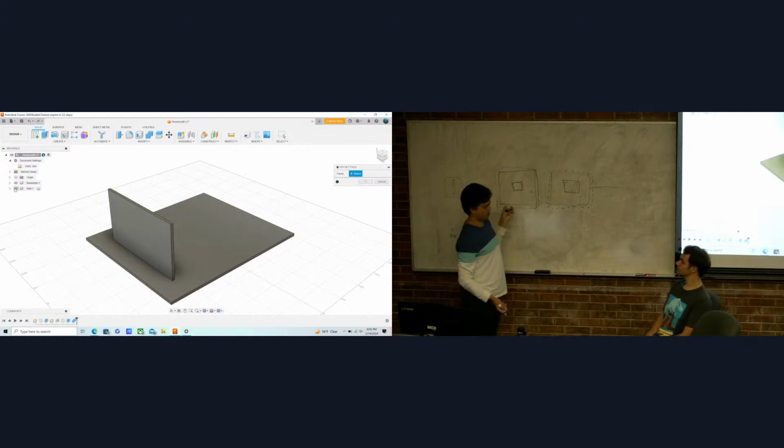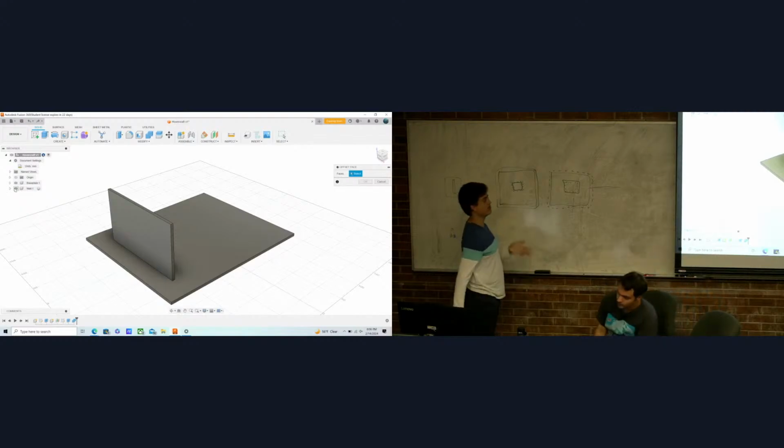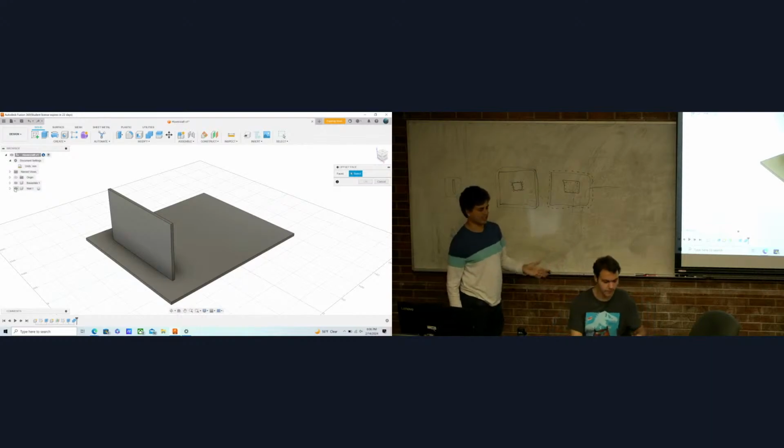And because we use precision wood that is 5 millimeters to a very high degree, if you make your hole 5 millimeters and then you cut it, the hole is actually ever so slightly larger than 5 millimeters, and it will fit perfectly fine into the 5 millimeter thick wood. So because we do laser cutting in wood, you do not have to offset anything. You can just make your holes exactly 5 millimeters using the combine tool, and it will assemble correctly.